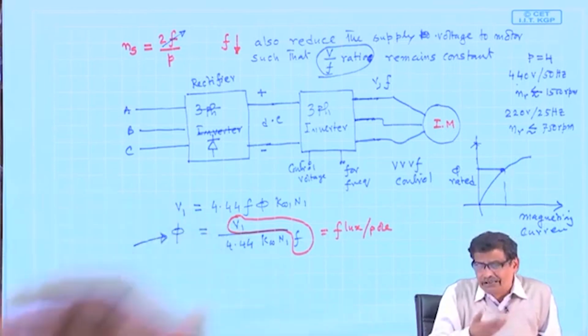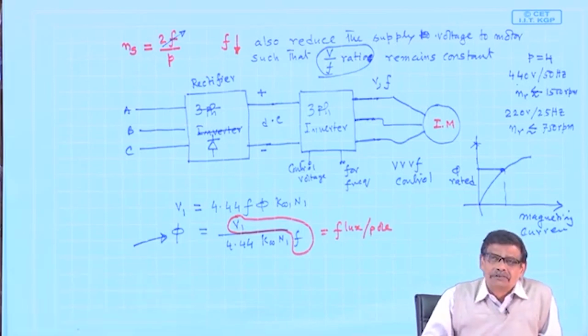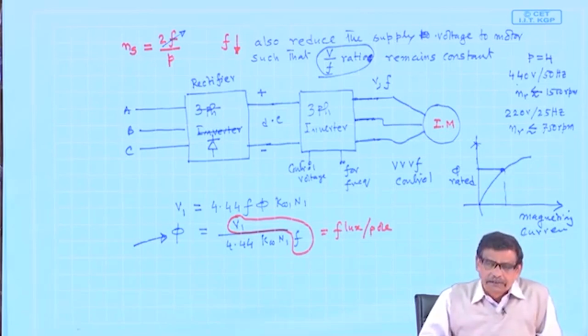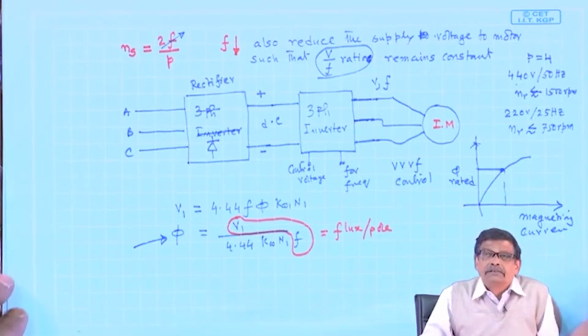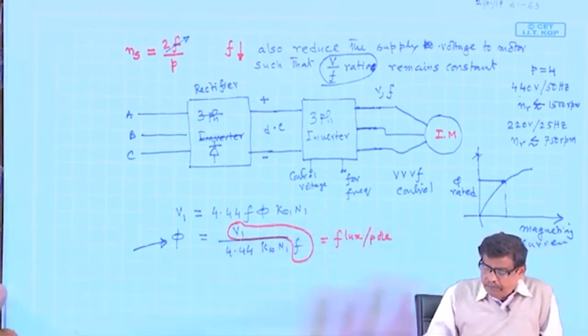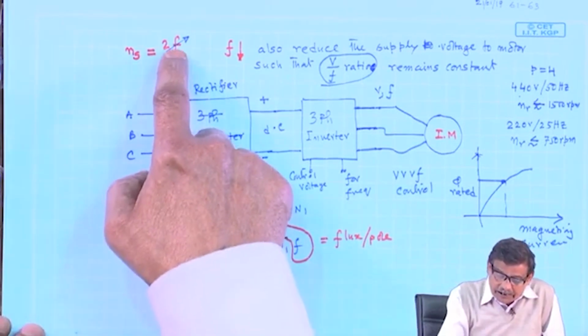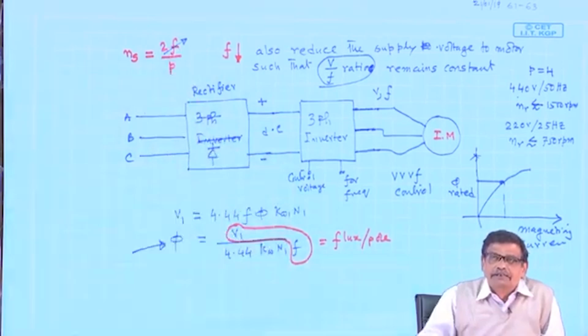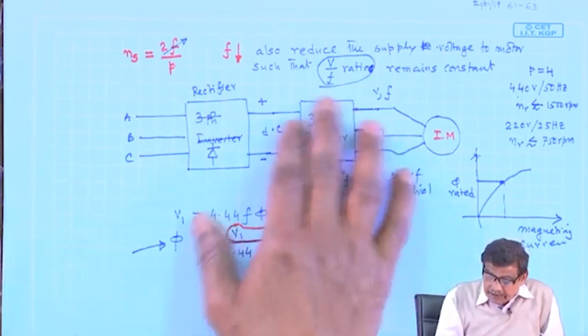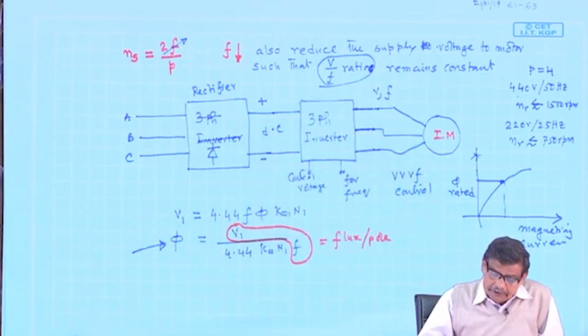Here you could control speed only at discrete levels, that too with complicated things like changing the number of poles, because the frequency of the supply was fixed at 50 hertz. But nowadays those things have gone and you can control the speed nicely. The better option is to vary the frequency, and that can be done easily by modern day inverters.